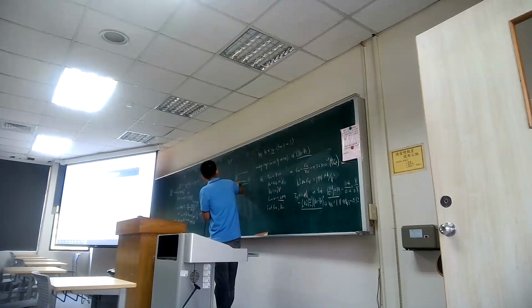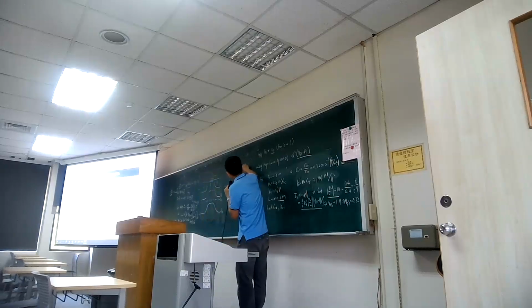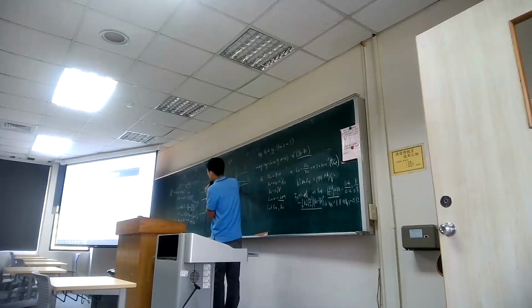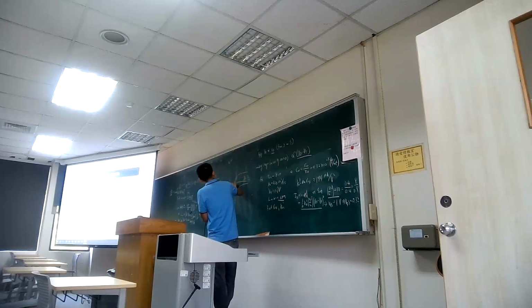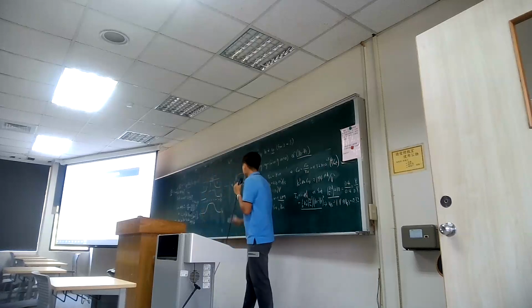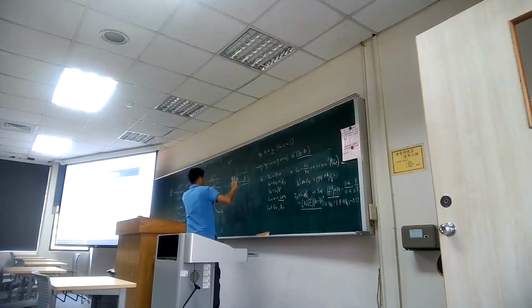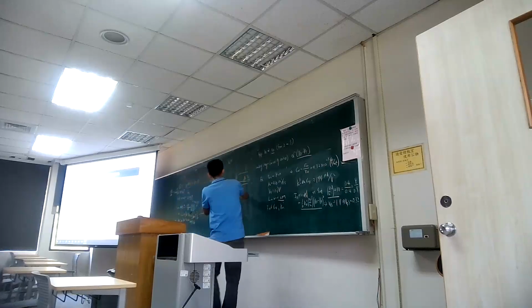And then since we apply positive voltage, we get a certain trap of electrons here. And then here is the intrinsic level, the Ei. The Fermi level here is in the P-type semiconductor, so at first it is below the intrinsic level. But later on, since we apply a higher gate voltage, what is the total? We assume initially it is flat band. So what is the surface potential? 2 phi B. So what is phi here? So here is 2 phi B. Okay, that is what we learned in the previous one.